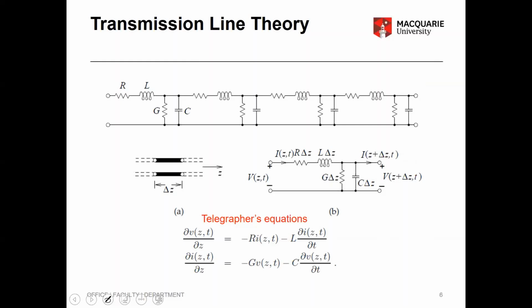So any transmission line, as is shown here, we can model as a resistance and a series inductance. The inductance stores magnetic energy, and the capacitor stores electric energy. So resistance and inductance are in series, and this is conductance, and the capacitance here are in parallel. Any transmission medium can be viewed as a repetition of these along a line.